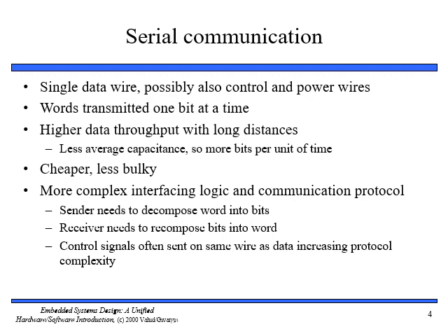Often both the transmitter and the receiver agree on the transmission speed used to send and receive data. After sending a start bit, the transmitter sends all n bits at the predetermined transmission speed. Likewise, on seeing a start bit, a receiver simply starts sampling the data at a predetermined frequency until all bits are assembled.